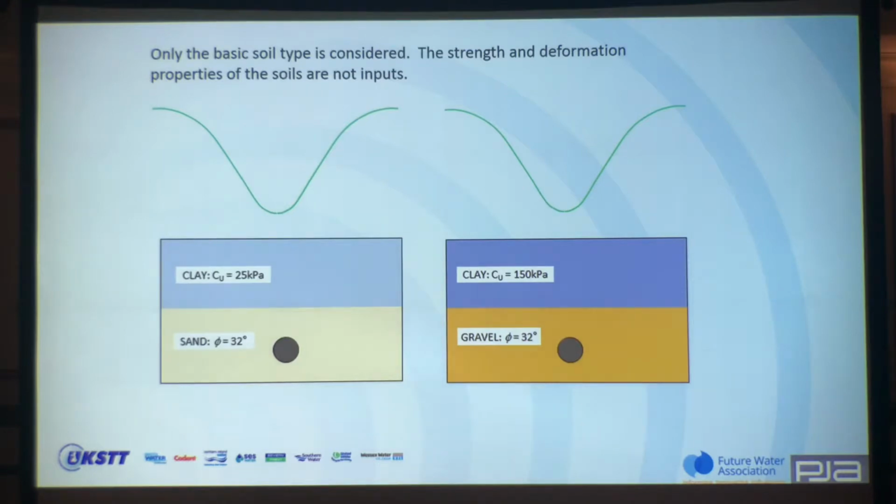So you can see here, if you're just considering the soil type, you've got a clay there, it's a soft clay, you can squeeze that between your fingers, 25 kPa, or a reasonable sand. You've got a very stiff clay, which you'd struggle to stick your fingernail in, and you get the same settlement values, same troughs, which isn't really representative. It's very, very conservative.